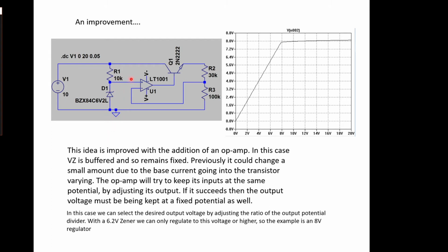So effectively what we're saying is that this voltage here needs to be bigger than the Zener voltage, but then we would always get a fixed voltage at this point here. And because there's no current drawn into the op-amp, there's no loading effects, so this voltage will not go up and down significantly, certainly not with output load anyway. Might go up a little bit with this.